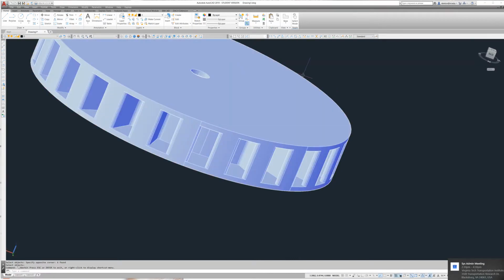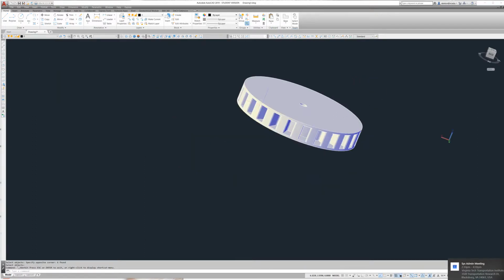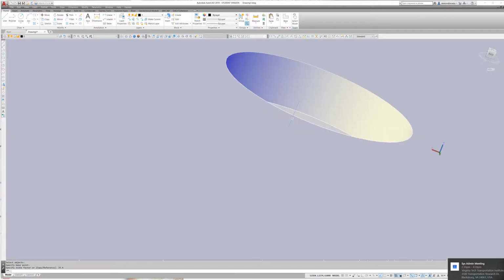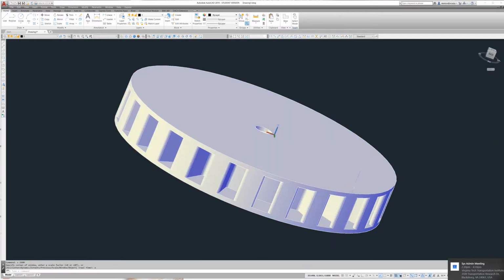Okay. Having created a part, I really need to save it. It's going to be a drawing. But before I do save this drawing, I drew it in inches. My 3D printer is metric. So the easy thing for me to do is to scale my part 25.4 times, and now my part is in millimeters. I scaled it up a factor of 25.4 to go from inches to millimeters.